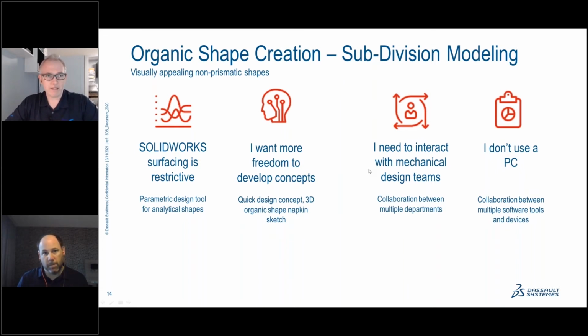And so what that means is that when you're using SOLIDWORKS, there's going to be a larger time investment to get that organic shape. It's fantastic tools. I mean, don't get me wrong, I used to use it to create fluffy furniture all the time, and I felt the pain with having to create all of the planes. You create your sketches in between the planes. You're going to loft those. You're going to sweep them. Okay, now we're going to cap the ends. So we're going to have 3D sketches and surfaces, and there's all sorts of tools to get that job done.